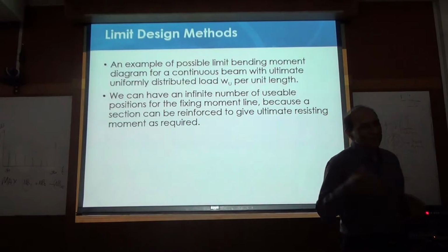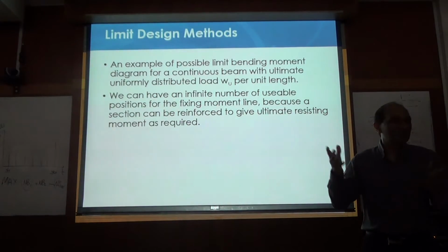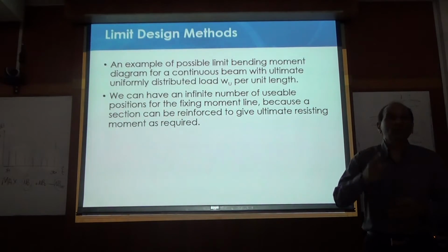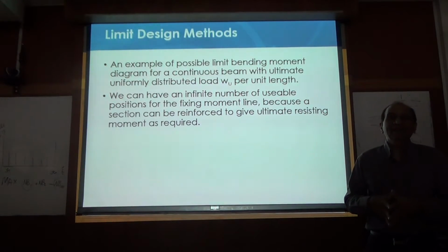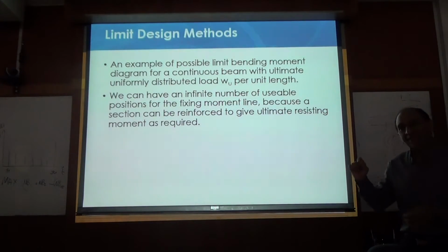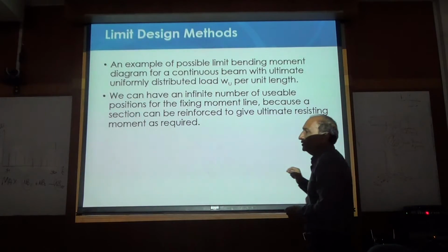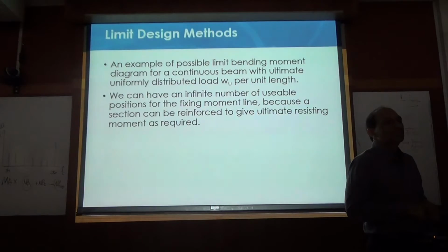Go tell your mom or your sister, at home in your living room, when your beam cracks, and she sees it and says, oh, the house is falling down, it's cracking. For the public, it is unacceptable. They cannot understand that cracking is normal. If you tell them that we design for cracking, they say you're crazy. Why don't you design one that does not crack? So cracking, although not harmful structurally, changes serviceability, appearance and perception.